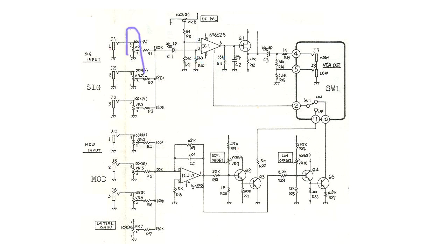Just for the moment, let's ignore the volume pots in front here. Basically, imagine that you've turned all of these pots all the way up, so they're not terribly relevant in the circuit. We're assuming that we're driving these inputs with ideal voltage sources, so the 100K resistance of the pot won't really matter if we have these pots turned all the way up. So then I have this resistive divider here. It's not quite obvious, but these input resistors are 180K. And let's see how much attenuation that gives us.